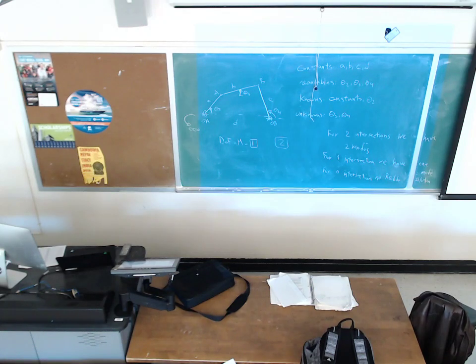But for point B, I don't know where it's going to be because I don't know this angle. For that reason, I'm looking for the solution. I draw a circle with this center and the radius of B. Any point in this circle can be a candidate for the position of point B. So it's not going to help me. I need to draw another circle with the center OB and the radius of C. It's going to be this circle. So the intersection of two circles, if there is any, has these two specifications.